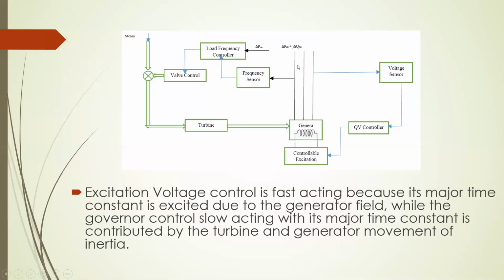Now according to the load, I have to sense the frequency value with a frequency sensor, right? This frequency value is given to the load frequency controller. We'll discuss what the load frequency controller is later. Previously it was 50 Hertz. With the change in demand, the frequency is reduced to 49.8. So the 49.8 value is given to this load frequency controller.